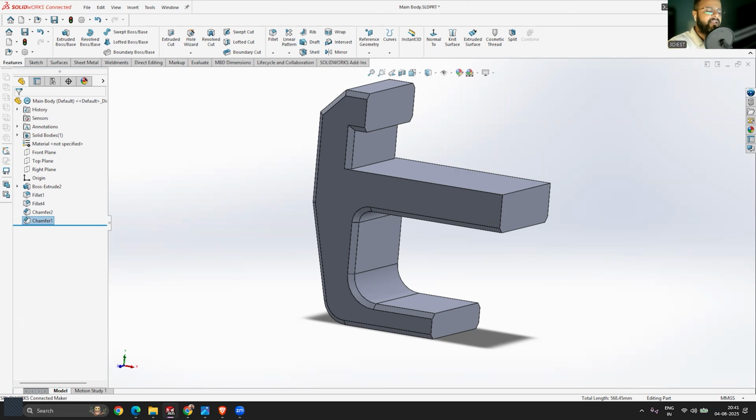Always apply, because if you make the corners super sharp, like at 90-degree, whenever you try to produce these rendered images, the lights may not reflect correctly, or you will get not very good rendering results. So to make your renders look more realistic, always apply some sort of fillet onto each of the sharp edges of your design, right?